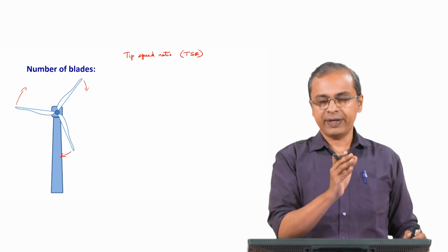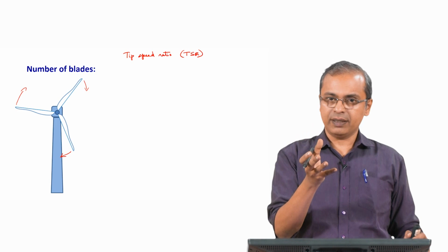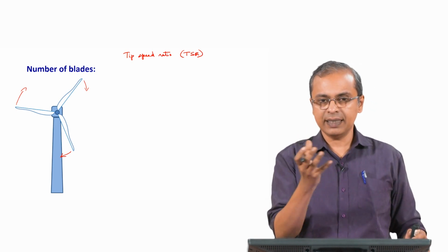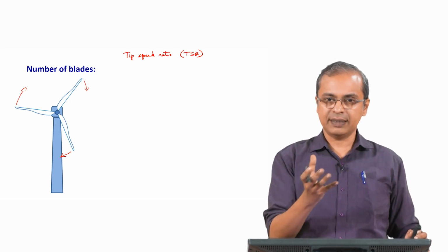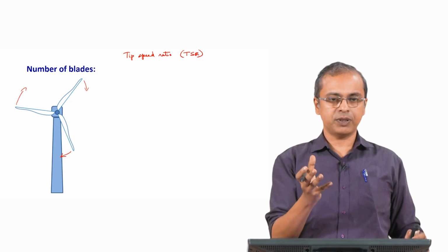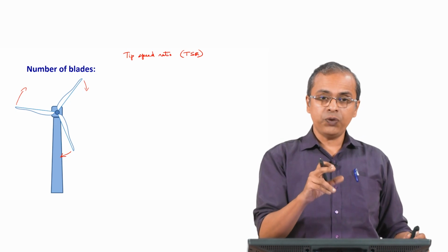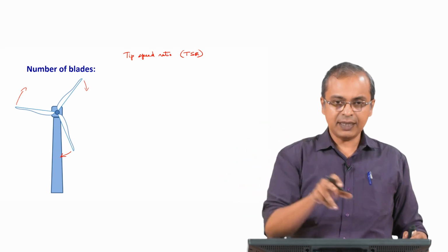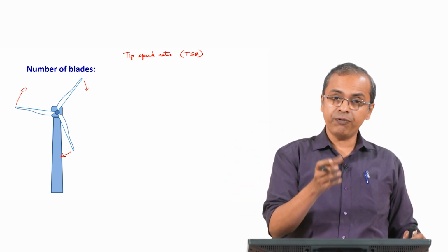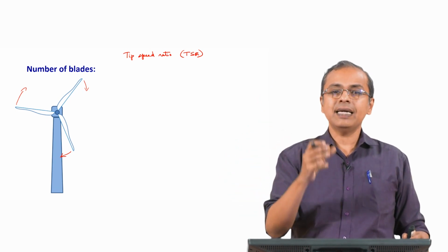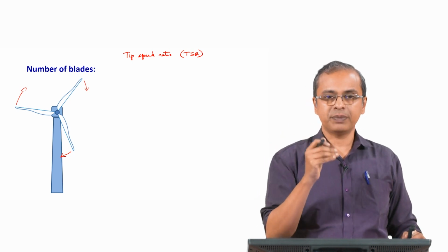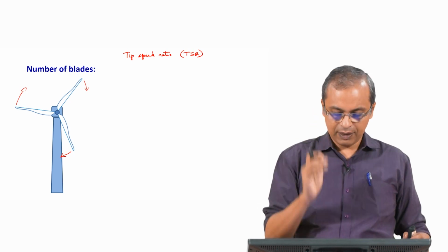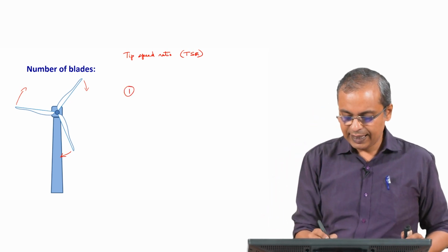Now, as the blade moves away, it has locally disturbed the wind, right. So, there has been an interaction between the wind and the blade, and that has resulted in some disturbed wind. So, some turbulent wind is there. So, you had some smooth wind going, you had some turbulent wind. Now, if you have the next blade of the turbine arrive at that spot before this turbulence goes away, then the next blade cannot completely benefit from the flowing wind.